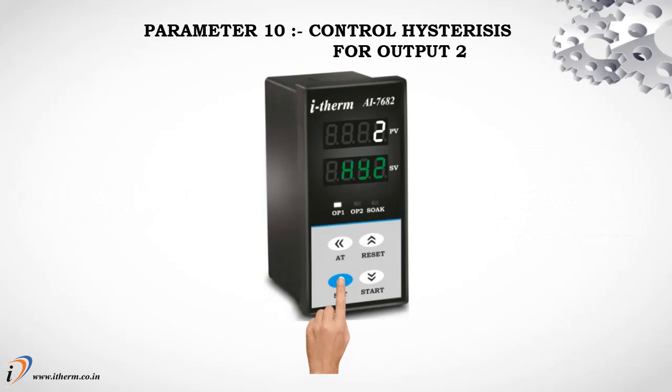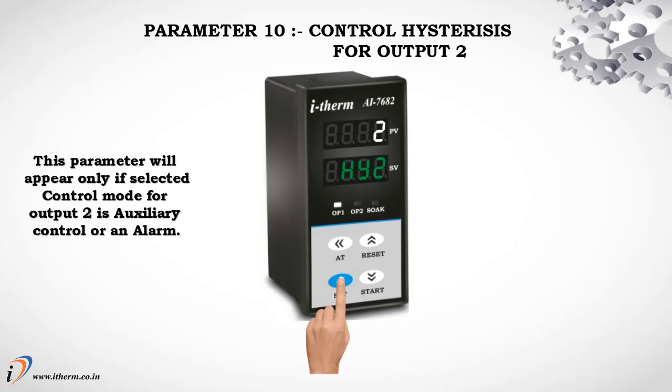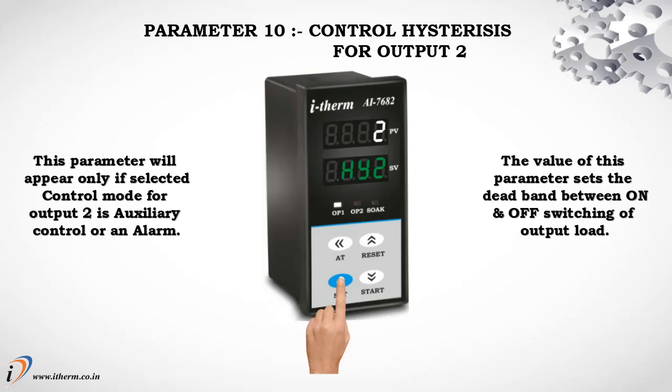Parameter 10, Control Hysteresis for output 2. This parameter will appear only if selected control mode for output 2 is auxiliary control or an alarm. The value of this parameter sets the dead band between on and off switching of output load.